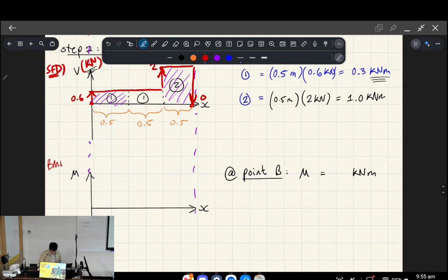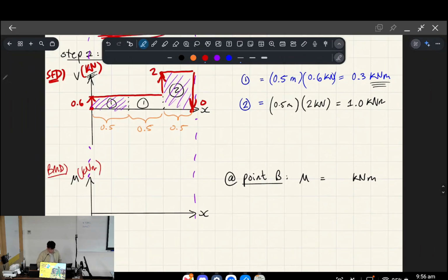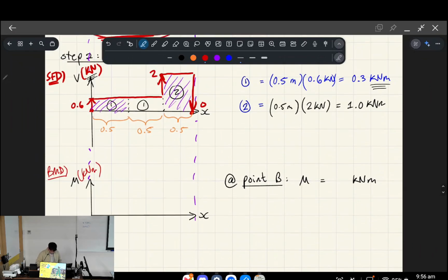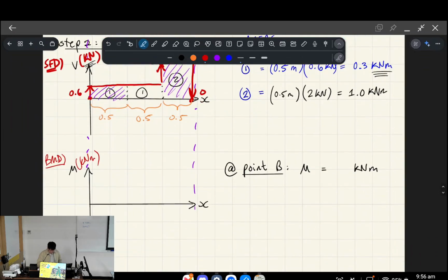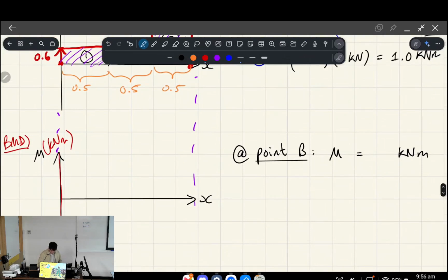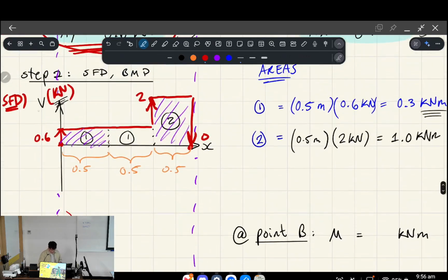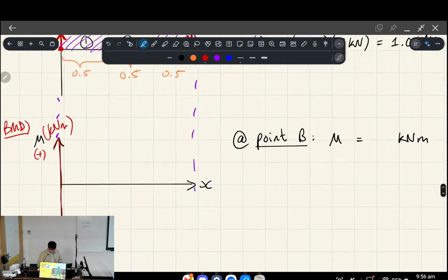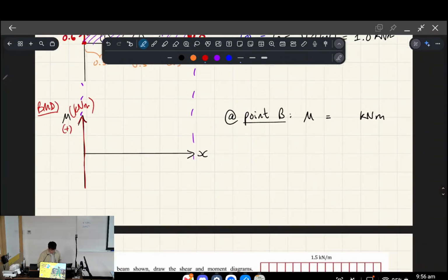So now we're going to do the bending moment diagram, and we're going to graph it in kilonewton meters. The first thing to note, and I know this might seem really obvious to you guys right now, is that the upwards direction that I'm going to graph is positive, just as it was here. The reason that's not obvious if you do civil engineering later is that it's actually more conventional to have the positive direction going down for beams.